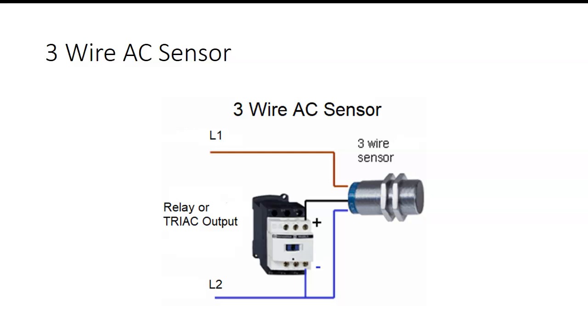So if I hook up those wires backwards, then it's not going to work. So what type of sensor would this be? So my PLC or my relay is using a negative common. So this guy right here's got to source, right? You understand that?